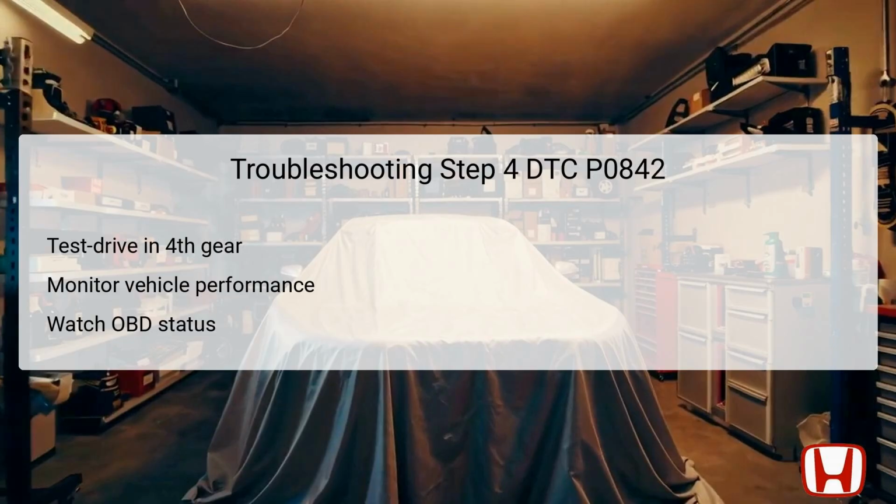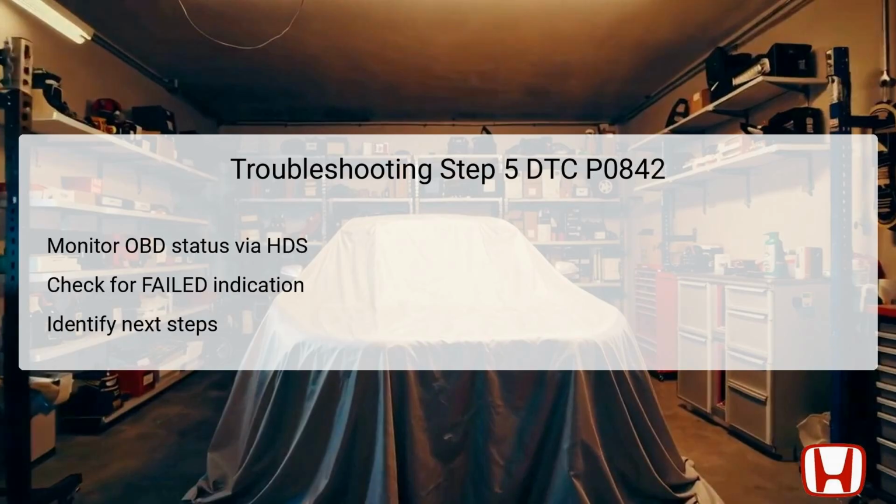This status will indicate whether the system has managed to resolve the issue or if the DTC is still active. Such monitoring is vital in verifying the success or persisting nature of any previous repairs. In this subsequent step, focus on monitoring the onboard diagnostic OBD status through the HDS for DTC P0842.